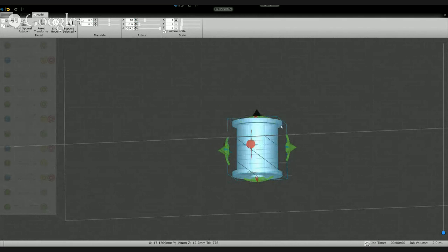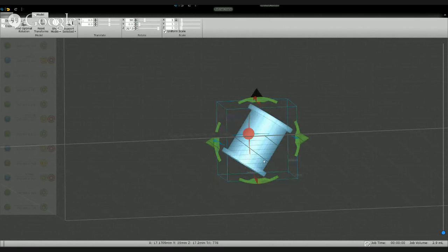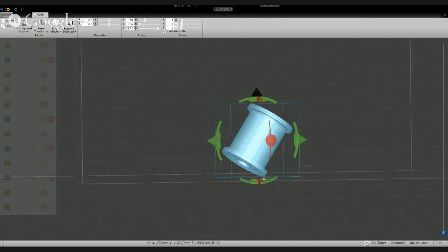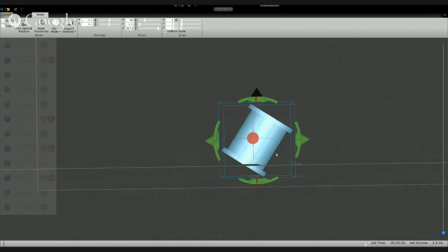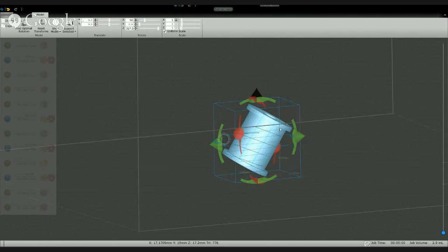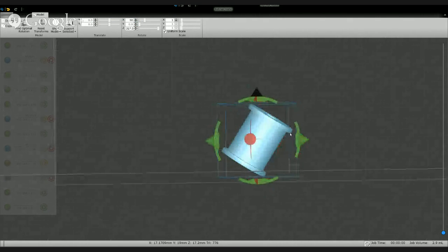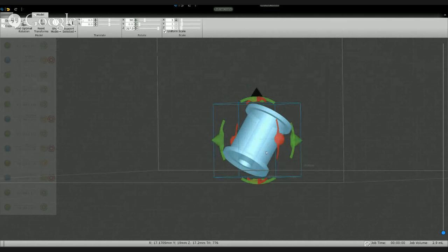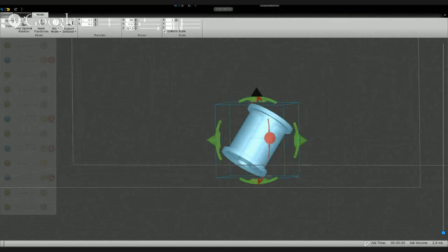There may be an ever so slight warp. So if that's a problem, then you'd also want to rotate like this. And now once you've rotated the model like this, you'll need some supports along here. You won't necessarily need supports along here. So the automatic support generator will create supports there, but you can just delete them. And you need a support here at the base. So we can either elevate the model and then manually support it, or we can do automatic supports.